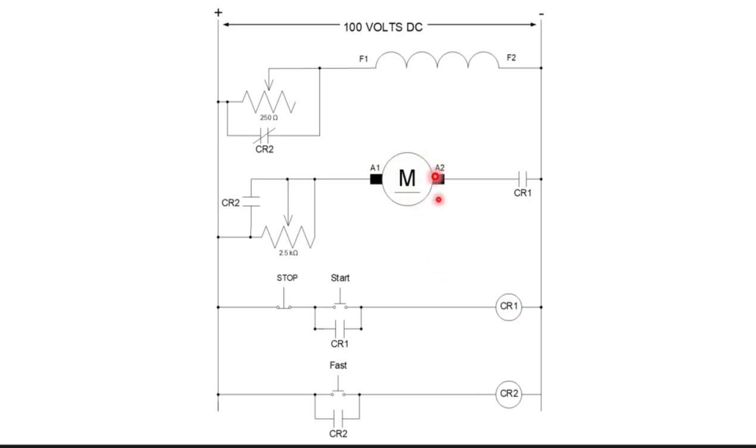motor to accelerate. So when we start a motor like this, typically what we do is start out by getting it up to its base speed. That's what we call it. We get it up to its base speed by controlling the armature current. Once we have it up at its base operating speed, we can further adjust the speed by regulating the field current. Again, lowering the current causes increases in motor speed.